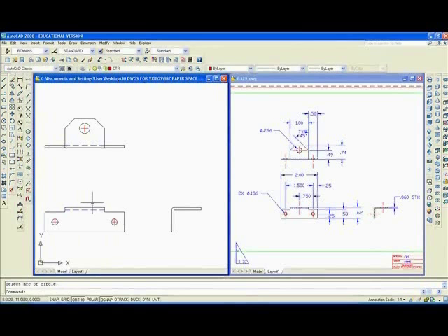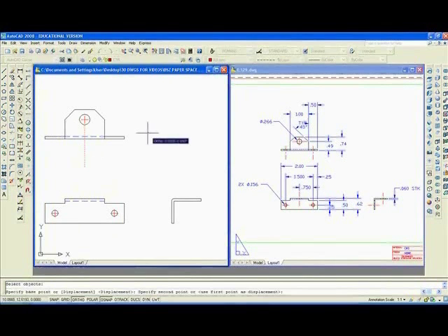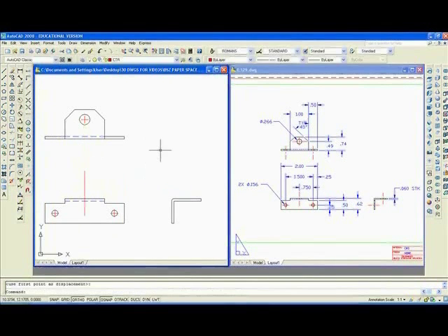And there. Actually, we want to draw a line down here like so, and then move it. Move that center line down here. I should try the LTS again. LTS. Oh, make it 0.4.